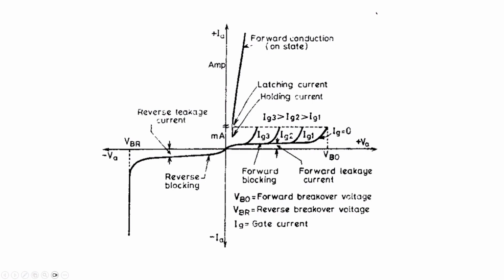Okay. So here, once the thyristor current, or the forward current from anode to cathode, crosses a particular value of current called latching current, then only the thyristor can be turned on. If the current value doesn't cross this latching current, and when you remove the gate pulse, okay, so first of all, the latching current can occur across the thyristor once you provide a gate pulse.